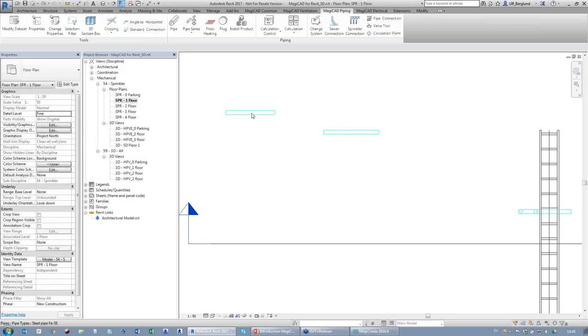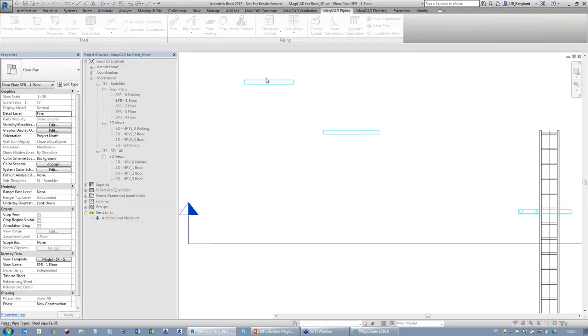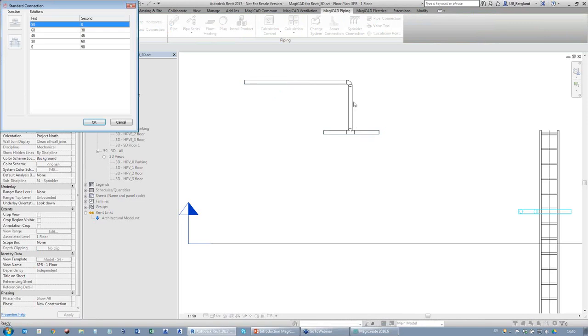Another thing we can do is that I can say, okay, I want to take this one, and with the standard connection, I want to connect that end to here. And then it will connect to there. And also here I can select these different types. For ventilation parts, we can also select if we want to have this as a T-branch or a tap. Obviously, we don't have that in the piping parts. But so if I create this like that, okay.